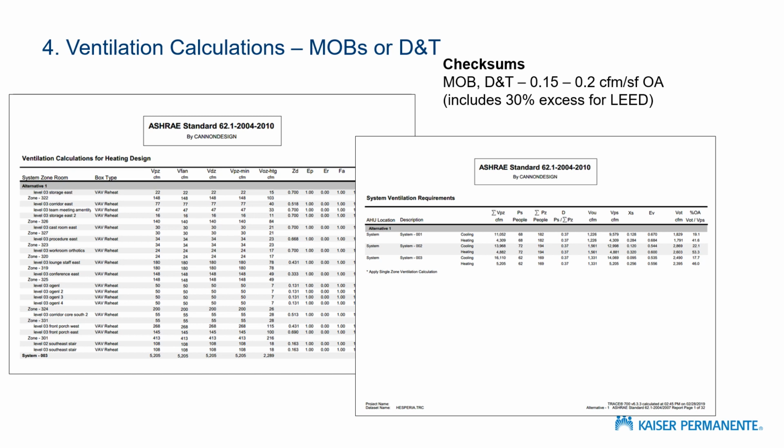Basically, we don't use those standards unless it's required by law, which means that in most of our outpatient clinics and medical office buildings and even D&T portions of inpatient clinics, we use Standard 62. I think every consulting engineering firm has some form of calculation methodology for Standard 62. Trace actually includes the calculation for Standard 62, so you can go ahead and use that.